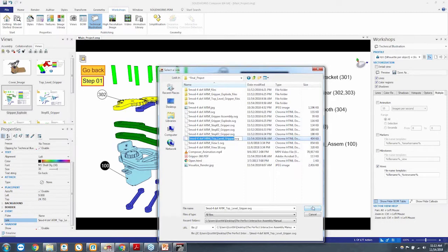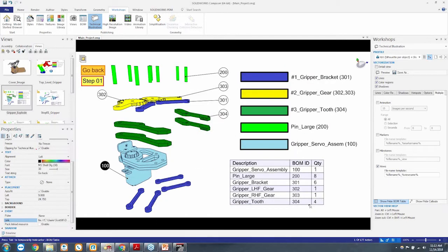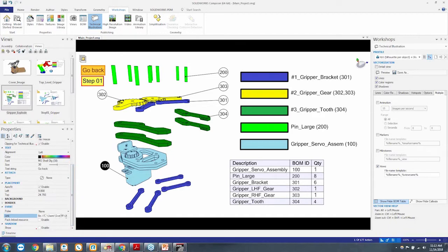I say OK. Now this is where things get a little bit not tricky, but just something to keep in mind. And this is one of those things we found out, and I just want to share it with you. It's a pretty good trick. So by default, you'll see that it's linking to that directory. I mean, it's file, C drive, my desktop, and it's SVG file. So now if I were to move that SVG file off my desktop, then all of a sudden this link would break, right? And by default, it's a direct link.